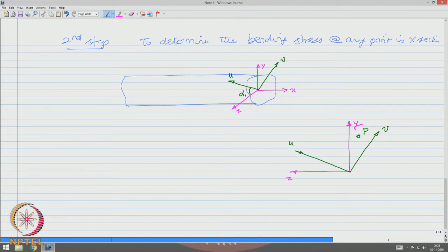Let us use a sign convention to mark the moments about an axis. We will use the right screw rule. So, let your thumb face the positive direction of the axis and try to screw along the axis like driving a screw with the help of a screwdriver.